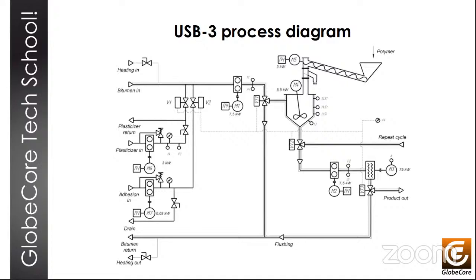and polymer is then evenly distributed in the bitumen, ground, and finally homogenized by the M3 mill. And from the M3 mill through the VT3 3-way valve, bitumen enters the modified bitumen line out to a product collection tank. So through the VT2 valve, the